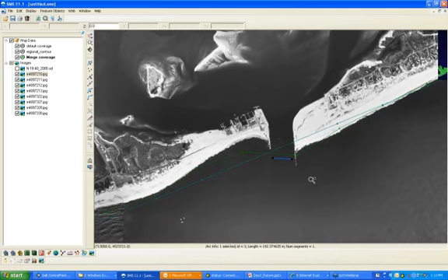The next thing we're going to do is develop our left and right jetties. And if you remember from yesterday, if you're sitting in the middle of the inlet, so you're here, and you're looking out towards the water, your left would be to your left. So this jetty here is considered your left jetty. So I'm going to go ahead and draw that by going to Create Feature Arc, and then just drawing the arc here.